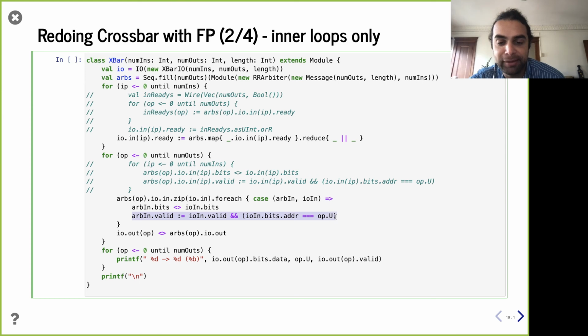So in this case, we actually don't even see the indices, right? The indices for these things are kind of hidden here. We had been using the for loop to materialize index space, and then we were using it to index into things. We index into things here for the arbiter in the first place, and then this implicitly has the right elements being passed around. So you actually need to materialize those indices. So yeah, that's pretty cool.